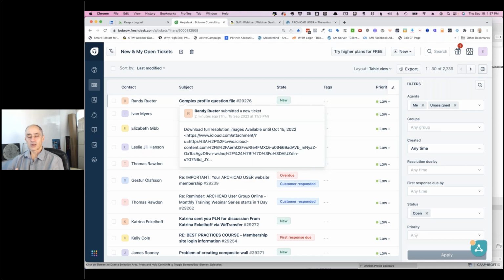Tom Palmer suggests putting it on a negative story that you don't normally look at, and maybe you exclude it in your 3D views and your sections, etc. That way, if you ever need to make a variation of it, you can go, like, that tabletop was a weird shape and maybe I want a different top shape, or I want to have thicker legs. I can go back to the raw materials, change them, or make a copy of them and change them, and then save a new version of the object.